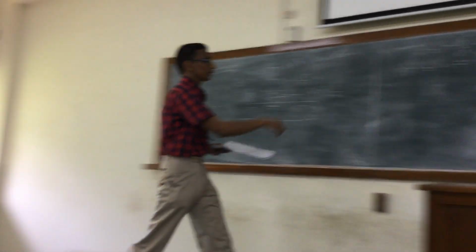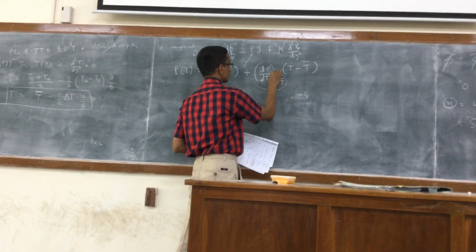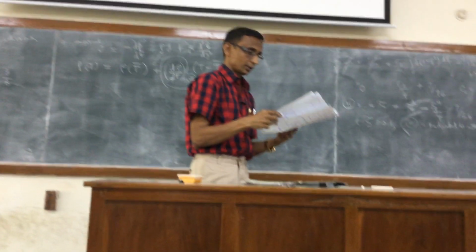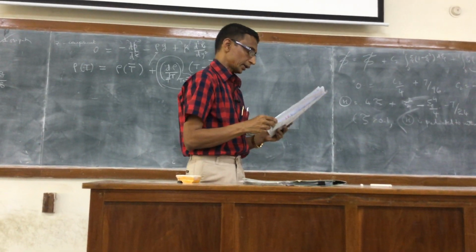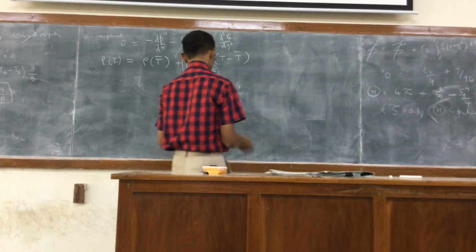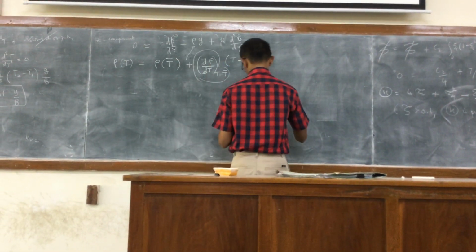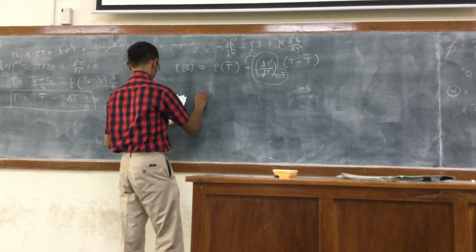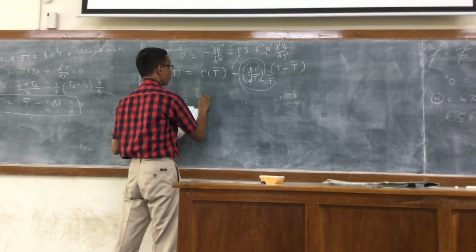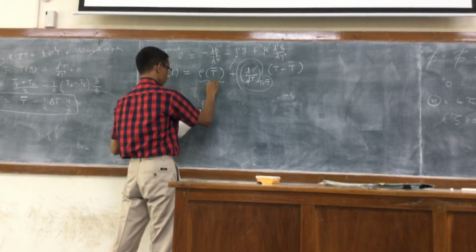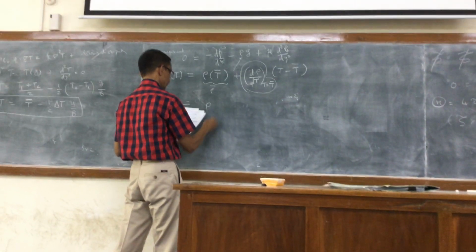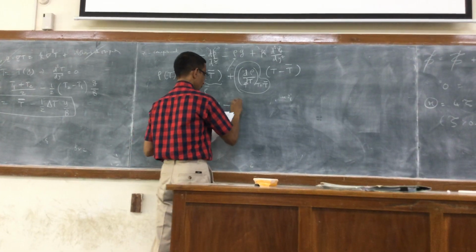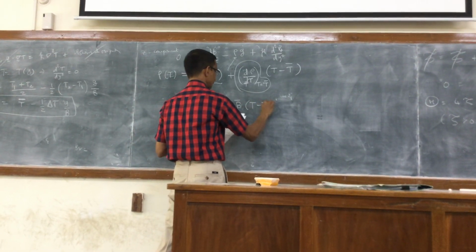However, this quantity d rho by dT is a thermodynamic quantity, because this is now effectively looking like a compressible fluid, right? And you can easily show that this can be written as rho bar, this I call rho bar, times 1 minus beta bar times T minus T bar.